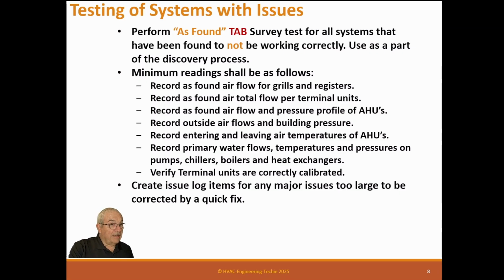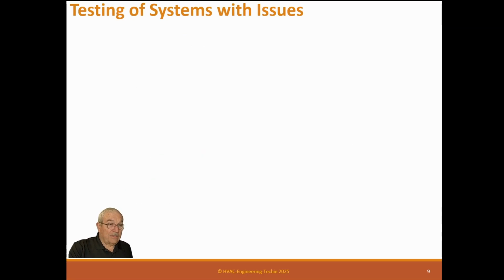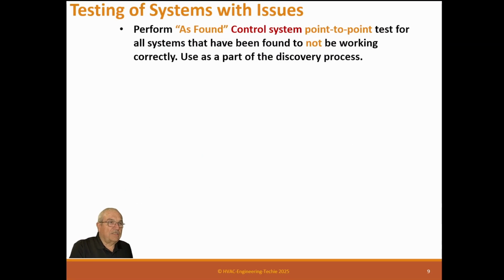So it's not like a capital improvement. It's a fix, but it's not a quick fix. Testing of systems with issue: perform as-found control system point-to-point tests for all systems that have been found not to be working correctly.